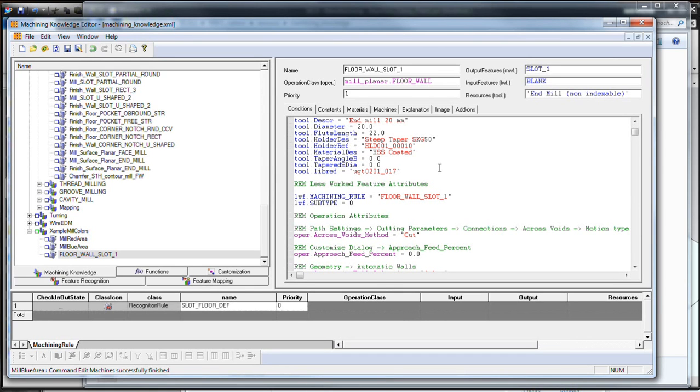If it is a tight diameter and position, you might have to bore that hole. So that would be the last operation. Then backing up from that, you're going to drill a hole that's going to prepare you for either boring or reaming, and then backing up from that, you're going to either spot or center drill that hole.